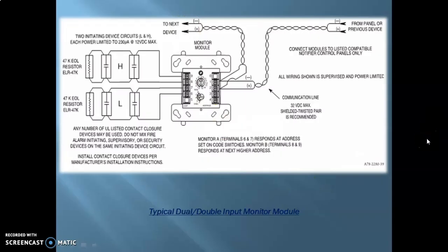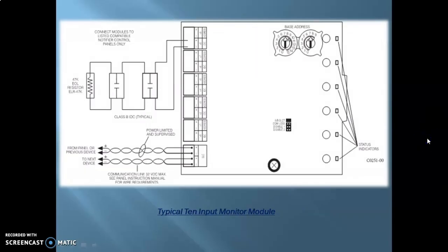Now moving on to the multiple input monitor modules. This is the example of a multiple input monitor module, basically a 10 input monitor module. This is what we'll be showing over here. As you can see, the SLC is shown over here, from the panel or the previous device and to the next device.